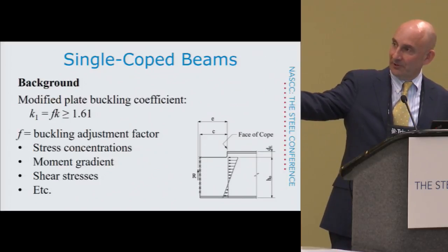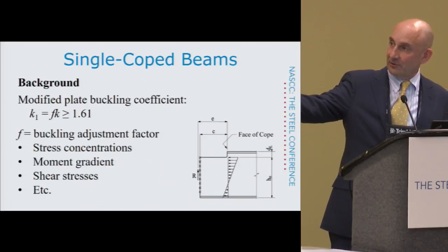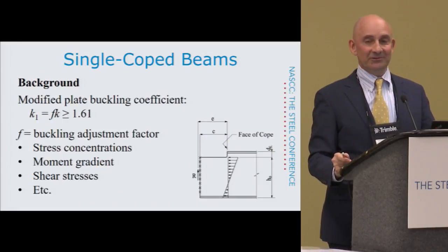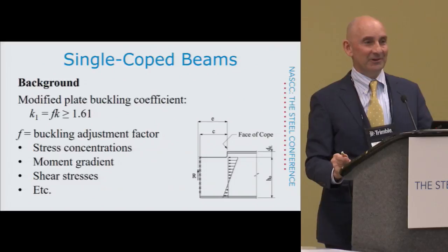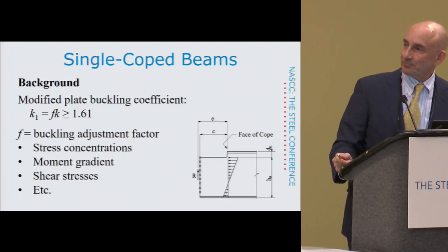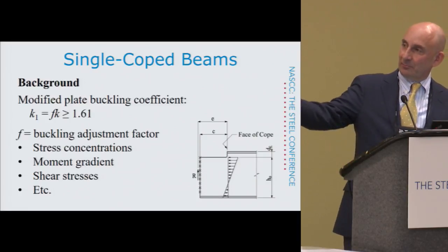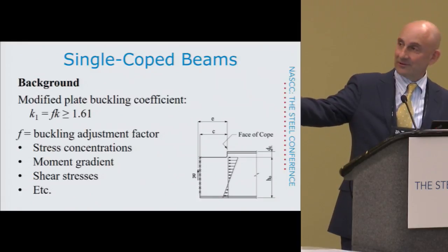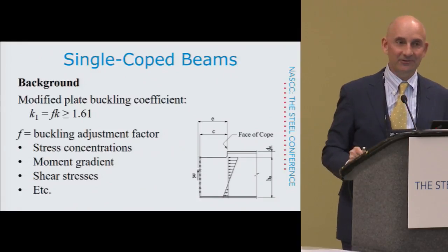For example, the plate buckling model has a rigid out-of-plane restraint along this line, and we don't have that here. If you're interested in these things, I would look at that University of Texas report. You can download it for free from the Ferguson lab there. If you look at the buckle shapes, some of these were curved. They buckled here, and they curved all the way in to over here, this far into the web. So obviously, we don't have lateral restraint at that location.